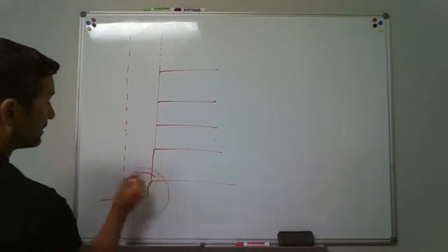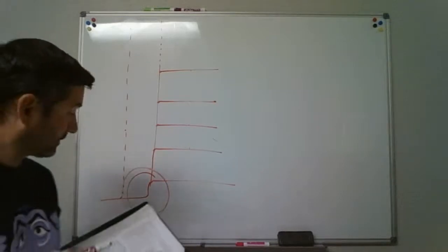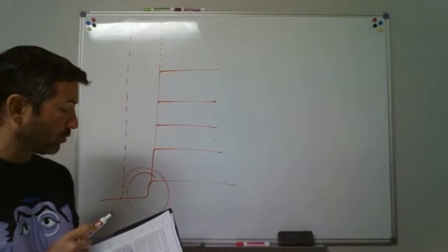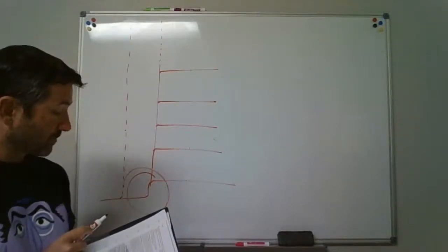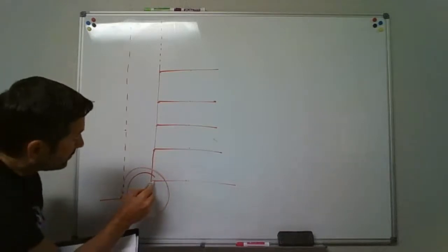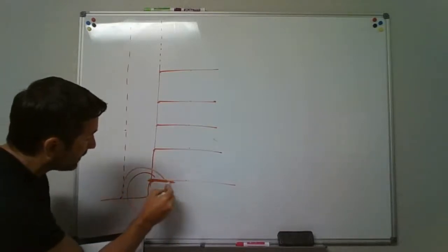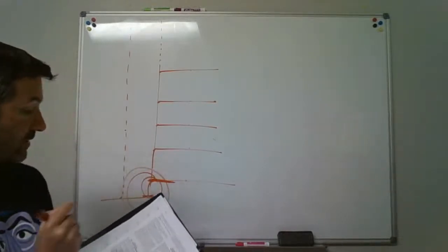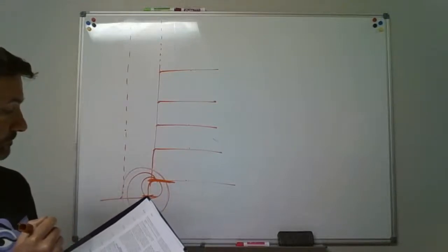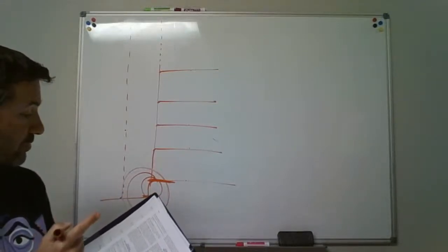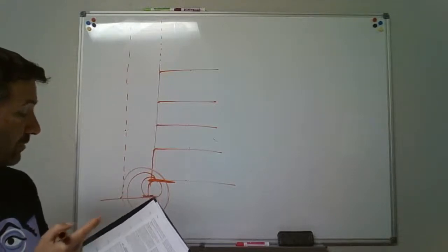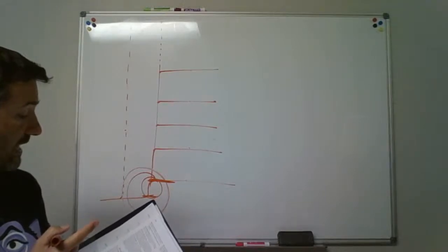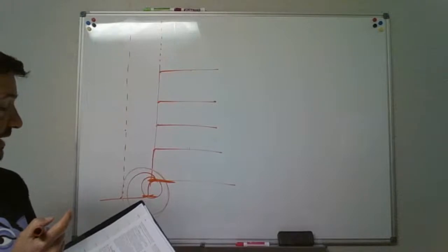Here's the base. Let's look and say, well, where at the base? The vent stack shall connect at or below the lowest horizontal branch. So at or below, here's the lowest horizontal branch, or below. So in this area in here, okay. Let's see what else it says. At or below the lowest horizontal branch, where the vent stack connects to the building drain, the connection should be located downstream of the drainage stack and within a distance of 10 times the diameter of the drainage stack.